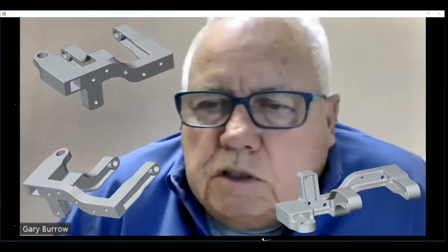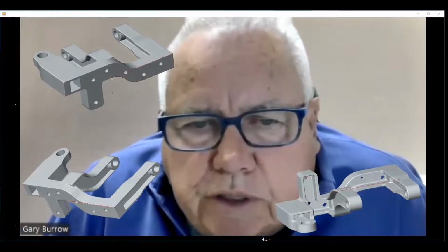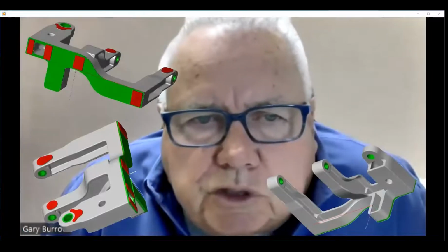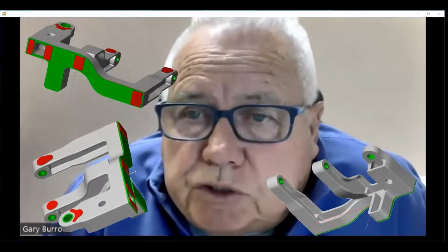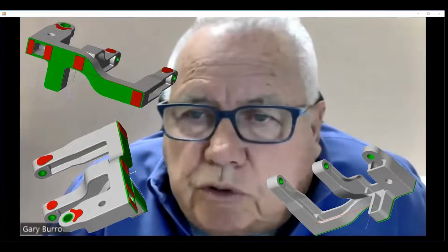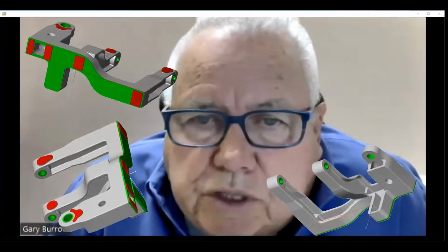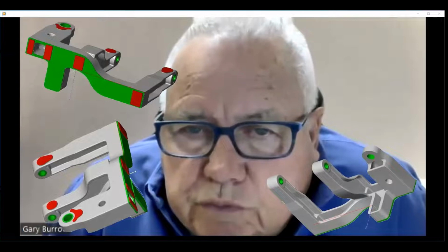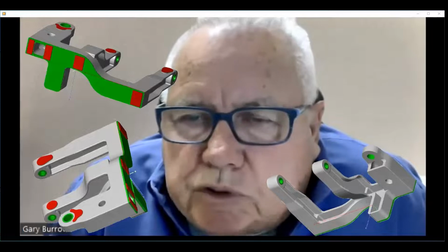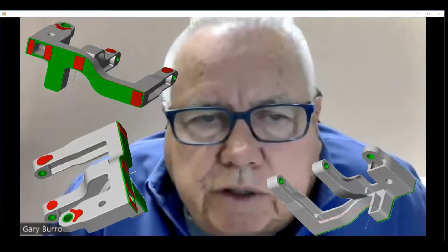As in our 2021 webinar part 1, we explained that there are 3 versions of the solid model, all built from 2D drawings: first, the legacy casting model, to replicate the 2D drawing; second, to build the mold cavity tooling and make the casting; and third, to machine the casting. Since the machining fixtures are dependent on the third solid model, it is prudent for the machine shop to collaborate with the mold cavity tooling builder in the design of these machining fixtures. That's basically to establish that the tool points are carried throughout the entire process.